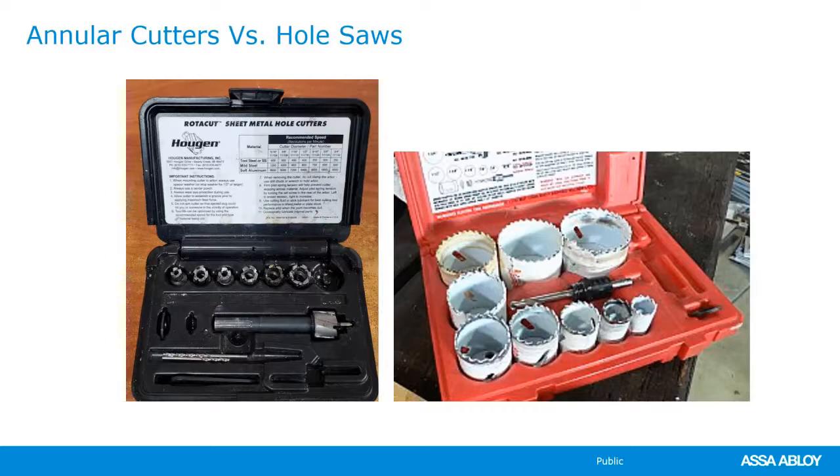And most people that have dealt with installation at all would recognize the little red kit there. That's a Milwaukee hole saw kit, and they're used for cutting all different types of material. They're used a lot to cut sheet metal, but they're not designed to cut sheet metal. And our doors, our hollow metal doors and our frames, well, they're made out of sheet metal. So hole saws typically cut a larger hole than you need. And when the hole is cut, it's not round.